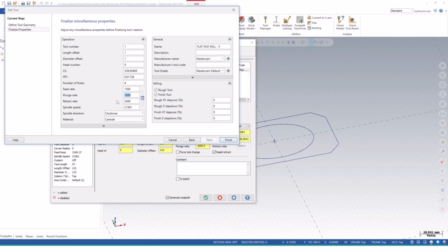You can calculate it by clicking on here to get by default cutting rate and the feed rate. So all these specifications from this to this area, where the cursor I'm hovering over, you have to calculate them according to your machine, according to your workpiece type, according to your cutting tool specifications.